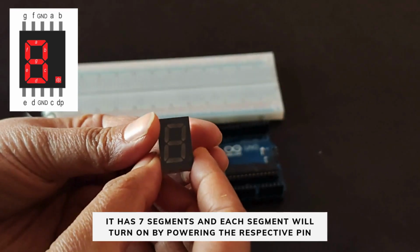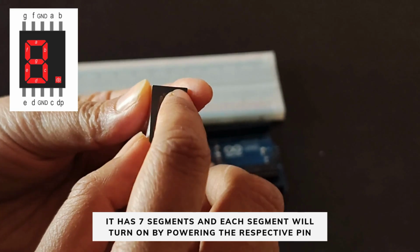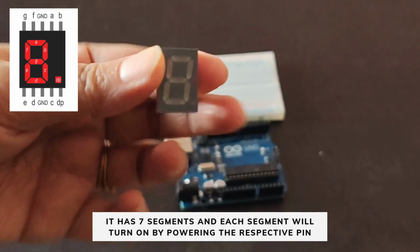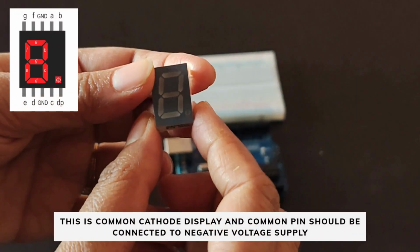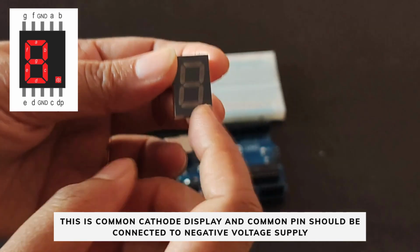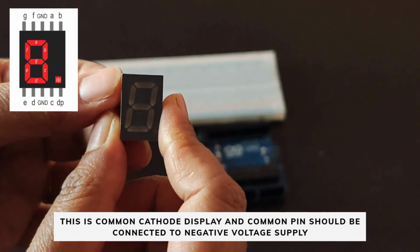So this is a 7-segment display. It has 7 segments here and each segment is attached to these particular pins. So when we give power supply to these pins, the particular segment turns on. And this is a common cathode 7-segment display. So here the common pin needs to be connected to the negative and the other pins need to be connected to the positive voltage supply.